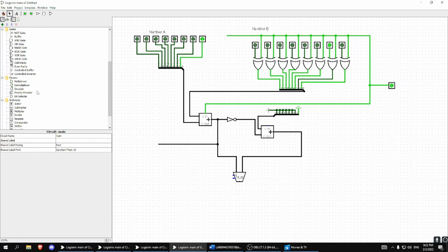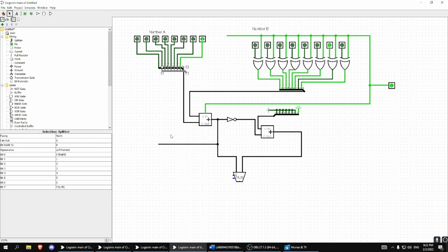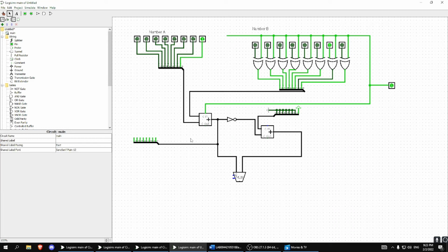So we could put this through a splitter again, just to show us it in 8 bits. So the splitter's right here. Actually, let's just copy this one. So it's like this right here. And we will take this last bit and we would choose which one we need. So since here it's 1 and it's negative, because the last bit is 1, we'll take this one instead of this one because it's 0 and 1.